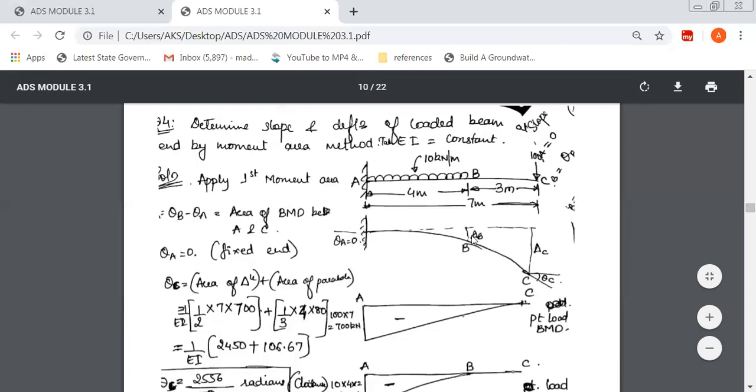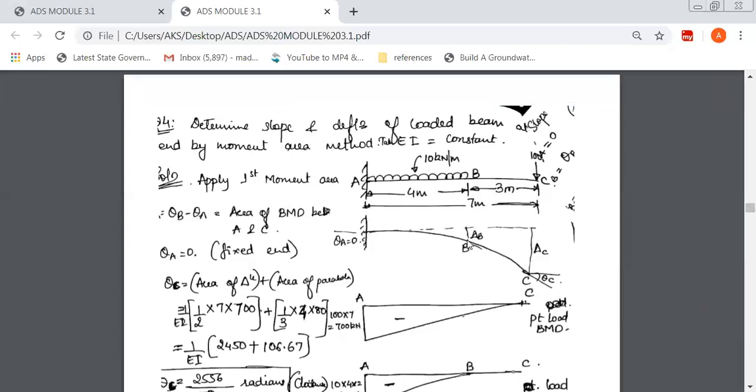Draw the original shape of the beam. So this is a dotted line. After that, you can check up to a certain length it runs straight, and after that the deflected portion of the beam is like this. Here at B it rotates and deflects less comparatively to point C, because C is the free end, and at the free end deflection and rotation are always maximum. You can see here, this is delta B, this is delta C, vertical displacement. If I draw a tangent here, this is theta B, and a tangent theta C.